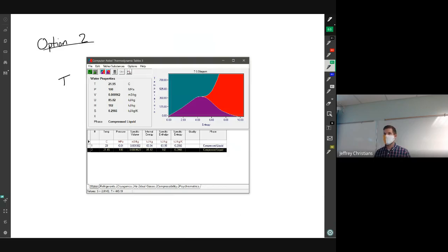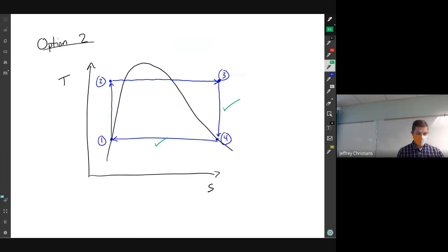It does change temperature, it does change enthalpy, it does change specific volume, it changes all of those things, but not very much, and not enough to give us an efficient cycle, right? We're thinking we want a large delta. This is our T cold. This is our T hot. We want that delta to be as large as possible. And if we're pumping a liquid, it's just not possible to get a big temperature difference.